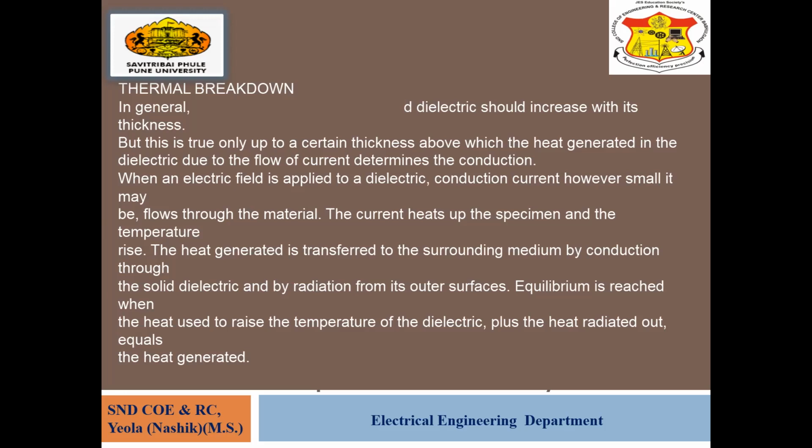When an electrical field is applied to a dielectric, a conduction current, however small it may be, flows through the material. The current heats up the specimen and the temperature increases. Heat is generated, the specimen is heated, and so the temperature increases. This generated heat is transferred to the surrounding medium by conduction through the solid dielectric and by radiation from its outer surfaces.